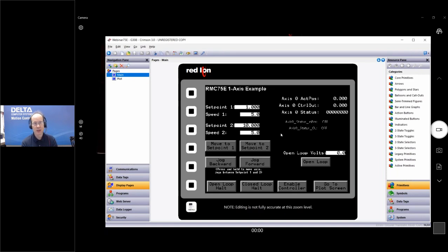We have to make sure that nothing else is accessing that during the same time. That's really hard to do with an HMI. So typically we try not to write to bits. Generally, you can set up a variable and just write that variable to be 1 or 0, or maybe have only a bit defined in there that you know the HMI is only writing to. And then, of course, we talked about recipes and scripting for sending commands, and then reading plots as well.